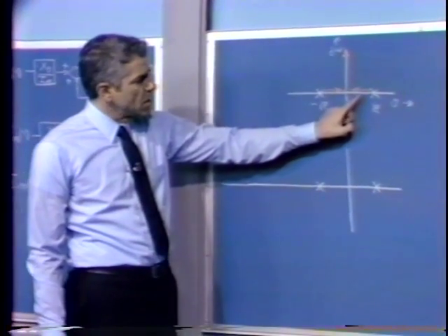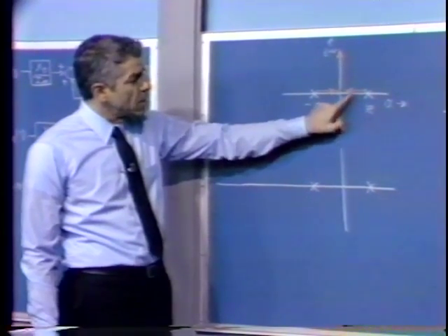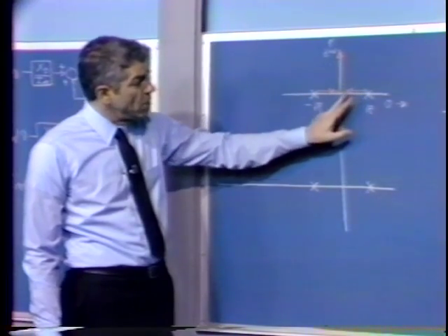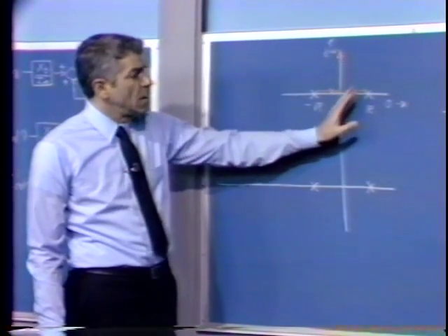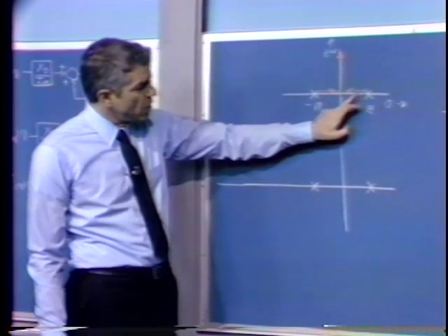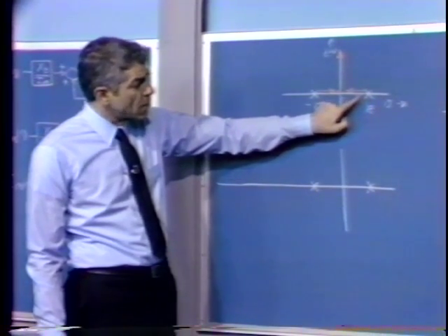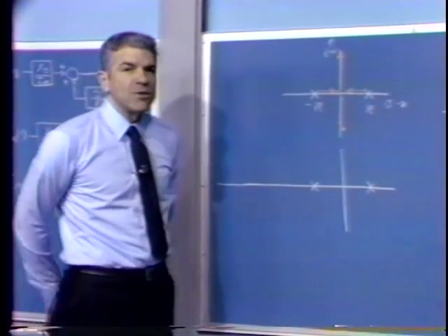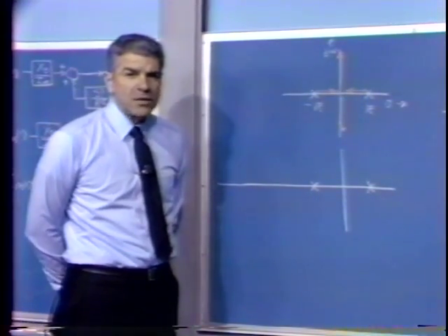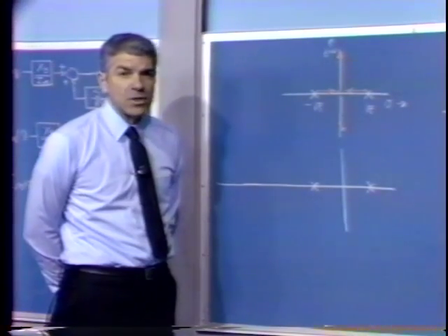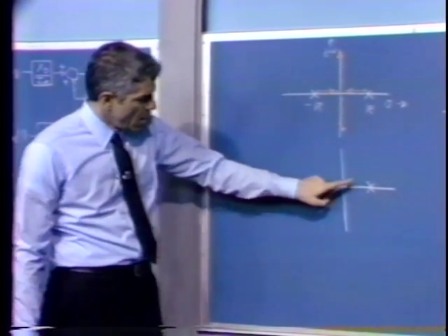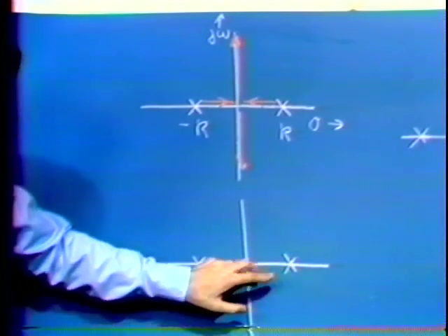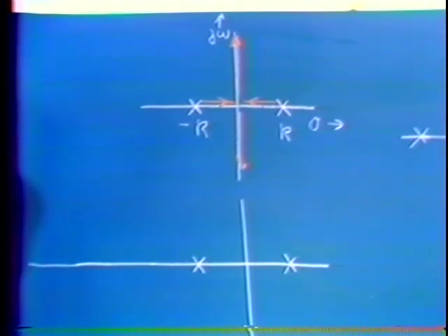If we start with a low value for A naught, we just don't move this pole even to the imaginary axis. And again, while we can bring this pole left, it still remains in the right half plane. And so this is a system where lowering loop transmission magnitude, which for many systems at least results in stable performance, fails. Well, let's see. Suppose we add a zero. That's a good thing to do.